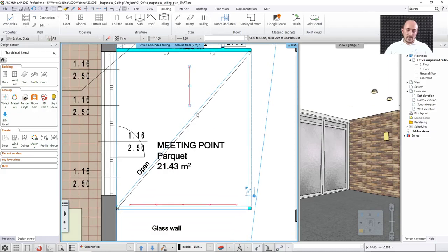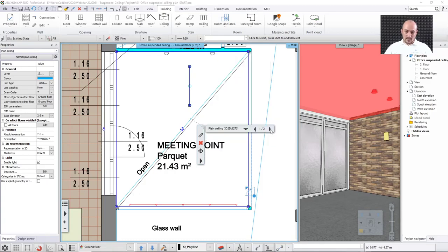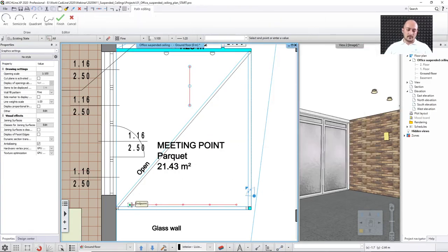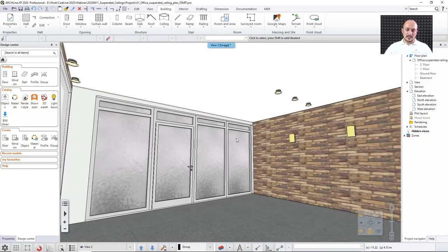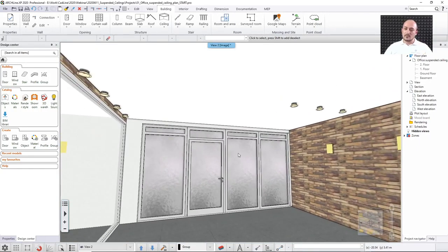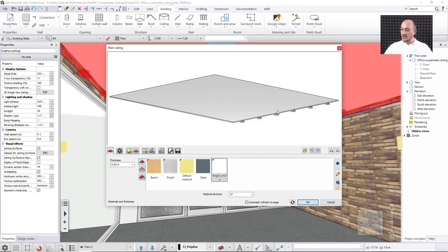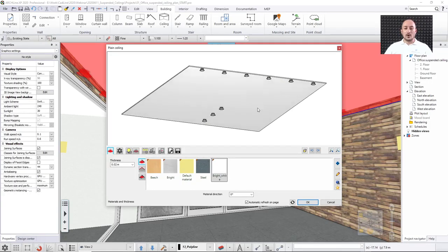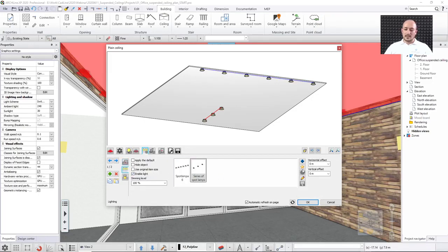I will customize this. And then I go here again, and choose add elements, add multiple lamps. Again, the same one, from this point to this point, and enter, and then I have those two. Now I can go to the details, to the settings. Okay, this needs some tweaking, but other than that, I already have those two distributed lamp series. Now let's go into the details and see what sort of settings you can set up. Again, just as in the case of the previous setting, you can decide to work on this one and say that you would like to sync them. Now, the vertical offset would be 0.04.